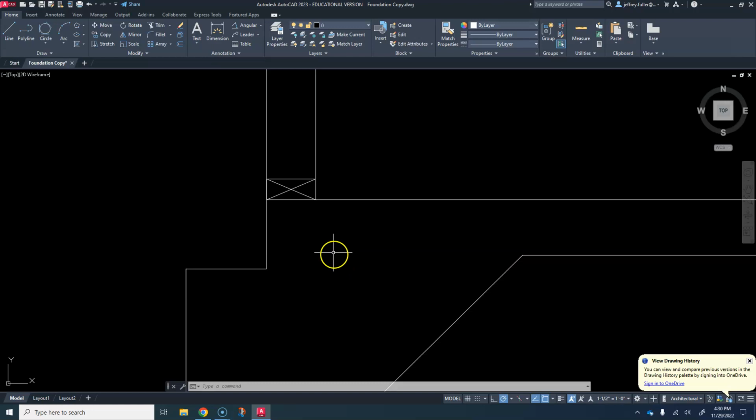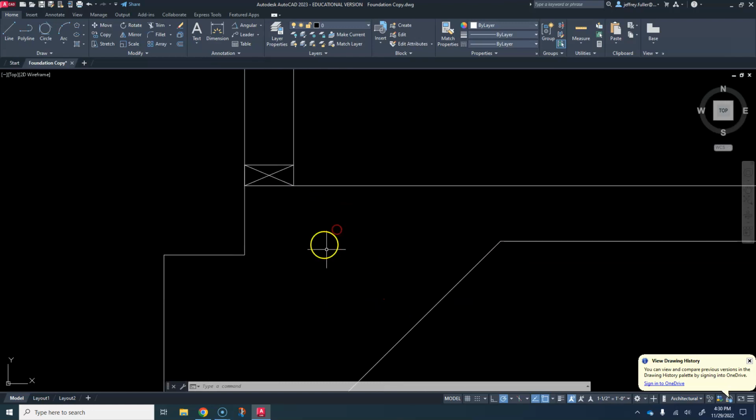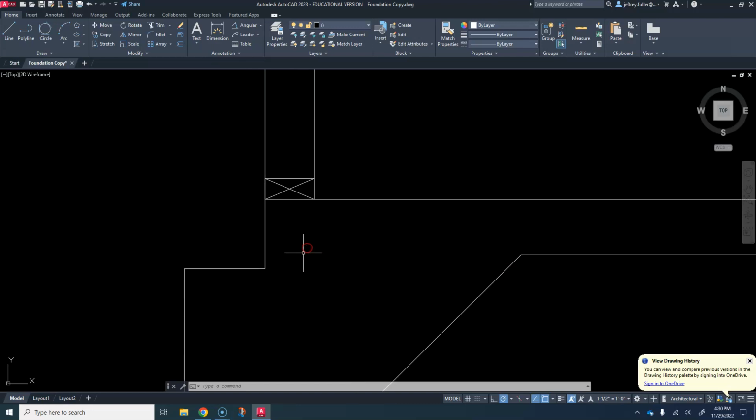Now I want to secure this wall to the floor system here, to this concrete slab, so I'm going to put an anchor bolt in here. It is specified that I have an anchor bolt that is 1/2, with a little inch symbol out to the side. That's 1/2 inch in diameter, 10 inches long, and it has to be sunk into the concrete 7 inches.